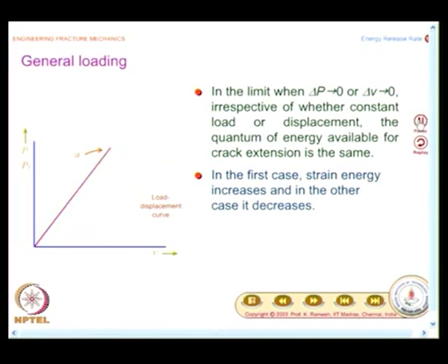So, both from a graphical perspective as well as from a mathematical perspective, the energy availability is same in the case of constant loading as well as constant displacement. Why do we switch between the two? The reason is, certain mathematical developments are easier to do in one of these cases, and also you could extend it for an experimental measurement. So, it provides a via media to apply fracture mechanics concepts to practical problems. So, this is the reason people have looked at it.